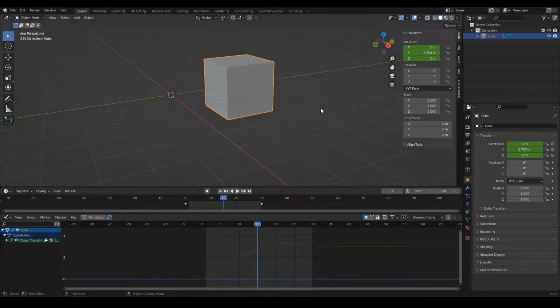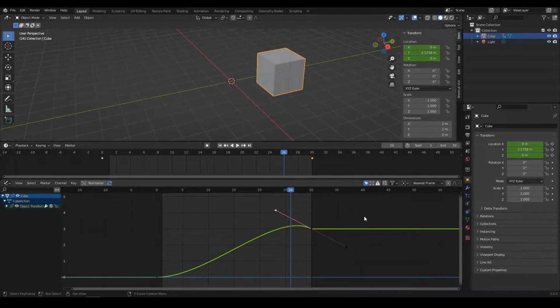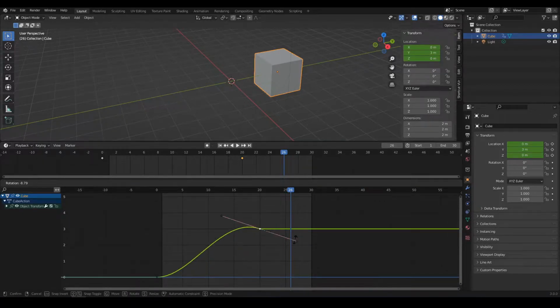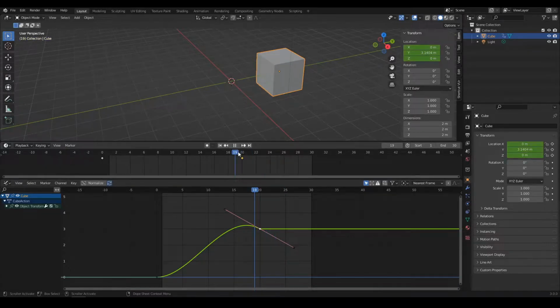Okay, next. Something else I need to mention, of course, once a keyframe is selected, you can also move it using the G key on your keyboard, like for an object. Okay, you can't rotate it, but if you, like for a curve, rotate in the graph editor, you will rotate the handle. Okay, and if you scale it, the starting point of the scale is the playhead, meaning that if